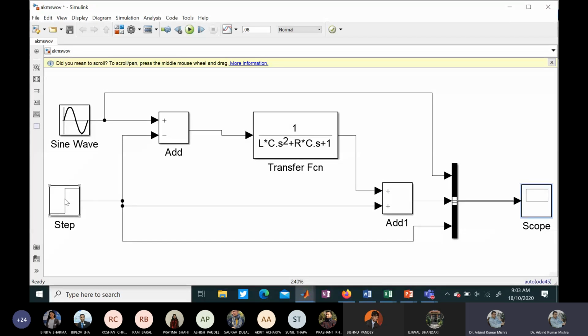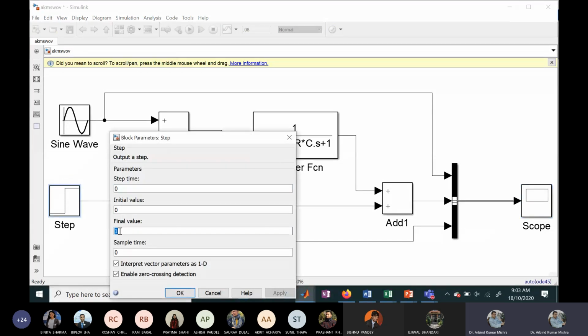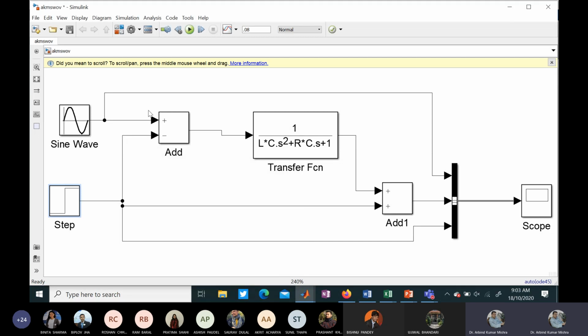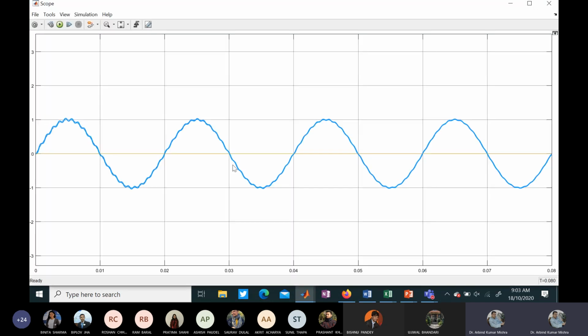Now, if I change just this, no trap charge, I have applied no trap charge, but the switching instant is again 0. If you run this simulation, you will see the difference. Without the trap charge, and with the switching instant at 0, there is almost no over voltage. That means even with the switching, the voltage across the capacitor is 1 pu itself,